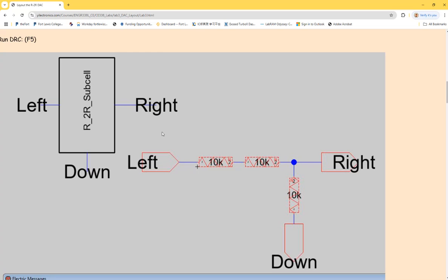So you create the icon. Electric nicely shows this icon view directly in the schematic view, which is just for your reference, which is a great feature, I think. I like it. But you don't want to directly edit the icon's details within that schematic view. It's just showing you a reference, but not telling anything else. Don't touch it. Go to the icon view. In the drop-down menu there will be a schematic view and an icon view. Double-click the icon view to get into it and edit the details. You can change the labels, the direction of the labels, size of the font, anything.